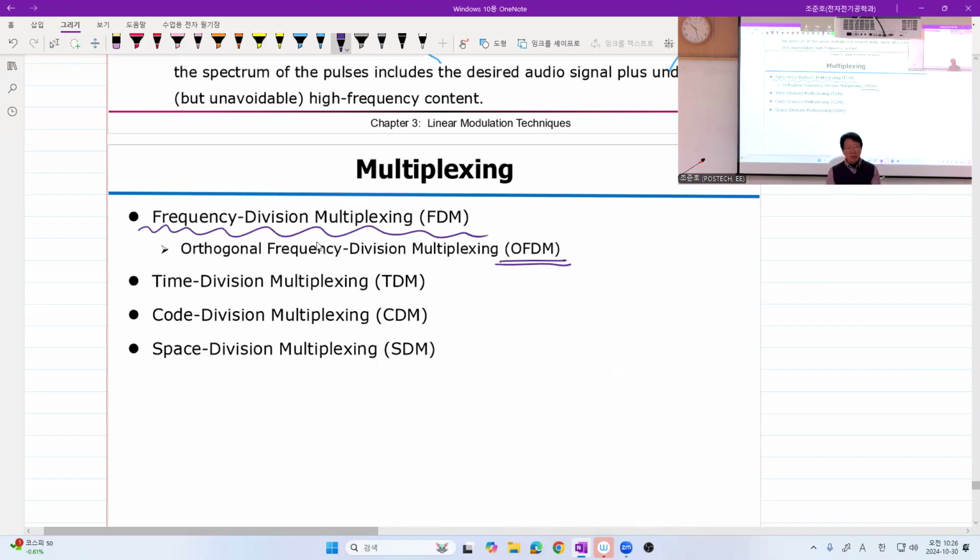So if you extend the integration of the product of two signals in the time domain, or using Parseval's relation in the frequency domain as an inner product, and if it is zero, then you define orthogonality, then frequency multiplexed signals are always orthogonal, right? Then why do we have this apparently redundant adjective in front of FDM?